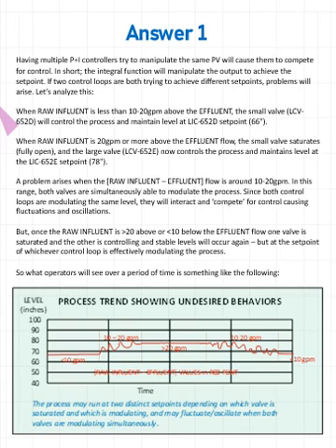And the graph at the bottom shows an illustrative example. I just sketched these, but it shows kind of what happens. If you look, you'll notice when it's less than 10 gallons a minute, because of the mismatch, the raw influent minus effluent values, when that mismatch is less than 10 gallons a minute, it's hanging out about 66 inches, pretty stable. When it's in between 10 and 20 gallon per minute mismatch, you get oscillations,